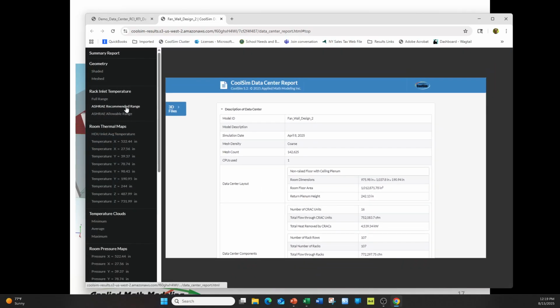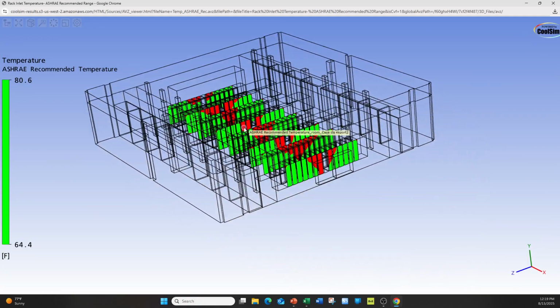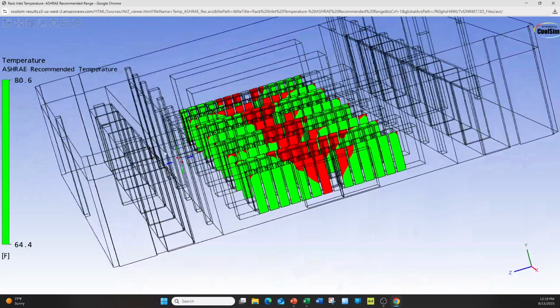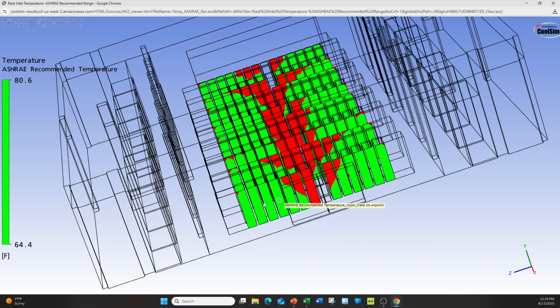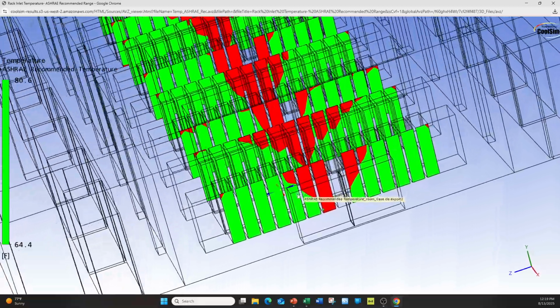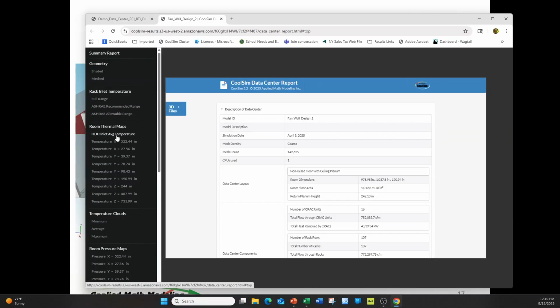This is going to show itself in rack inlet temperatures you see, and of course in the center is where you have some issues. Always in the center in these designs, because by the time you get to the center, the air is leaked by some of the servers, you don't have enough, and so you fall out of specification in the center. Same plots of supply air and return.